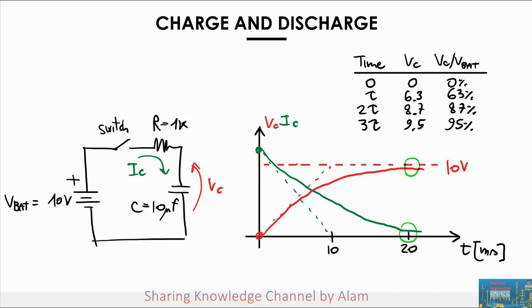To have an indication though of how fast the exponential waveform moves, that information is provided to you by the time constant. If you take two exponential waveforms that have exactly the same starting point and ending point but different time constants, they will look very different. So this curve that we can call curve A has an equation represented by 10 milliamp multiplied by e to the minus t over 10 milliseconds, right?